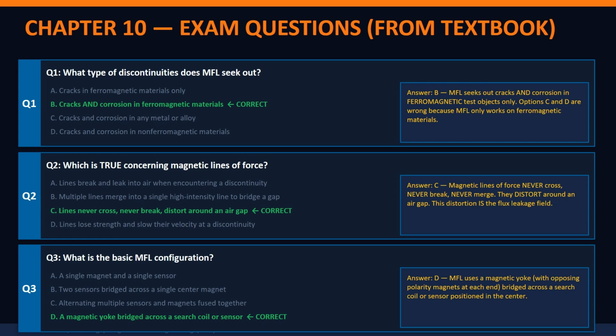Exam trap. Examiners often insert any metal as a distractor. That is wrong. MFL is limited to ferromagnetic materials.